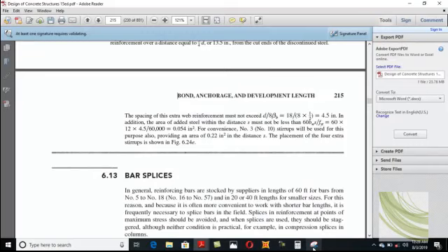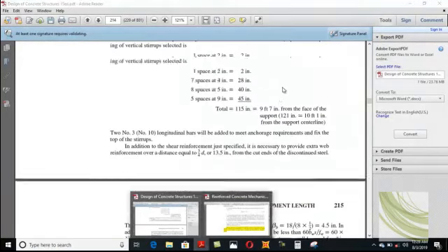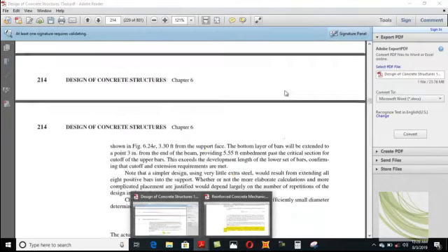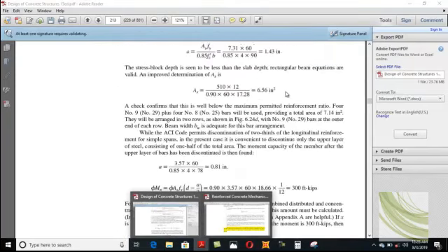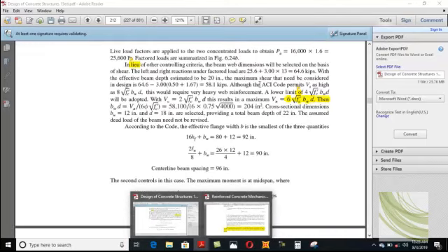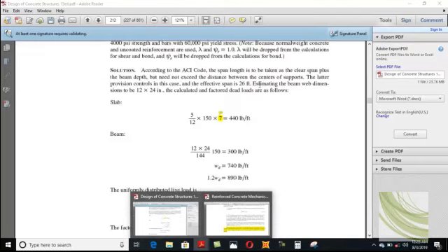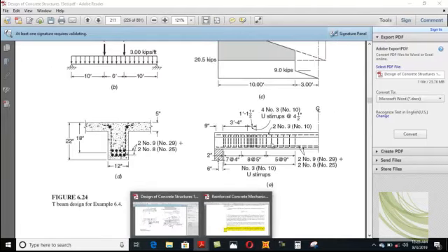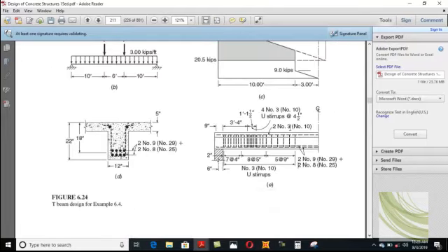Providing these extra stirrups, designers don't want to waste their time, and placing these extra stirrups needs some labor force as well. So there is a little bit of cost variation, so they say to continue the bars throughout the length. So in a simply supported beam, you can continue these bars, and that doesn't make any great changes. So I think this is the end.